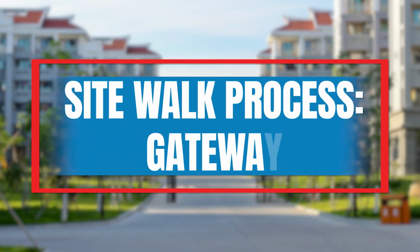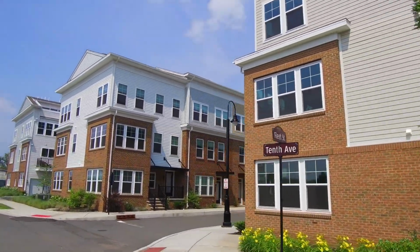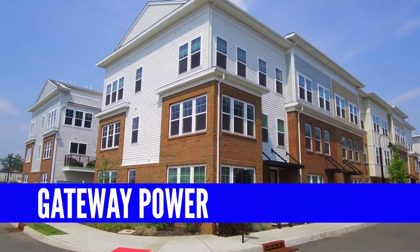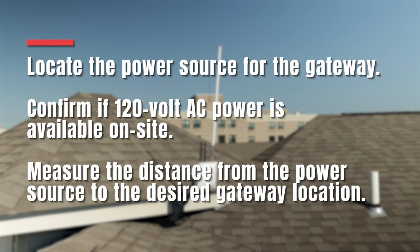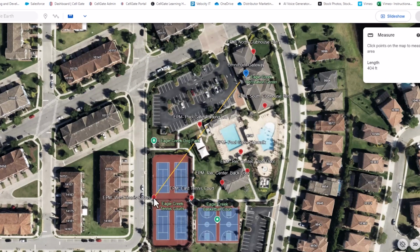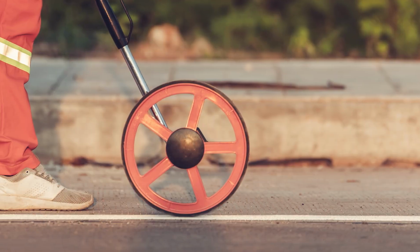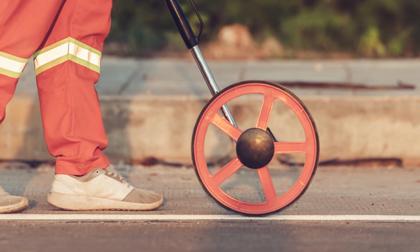Site walk process, gateway. Now that we're on site, let's focus on the OmniPoint gateway. Gateway power. Locate the power source for the gateway. Confirm with the property manager that 120-volt AC power is available on site. Measure the distance from the power source to the desired gateway location. Remember, if you're utilizing Google Earth, these measurements can be taken using their online tools. These measurements should be noted both on this fillable form as well as on that sitemap. To ensure this is accurate, you will likely want to use a measuring wheel.